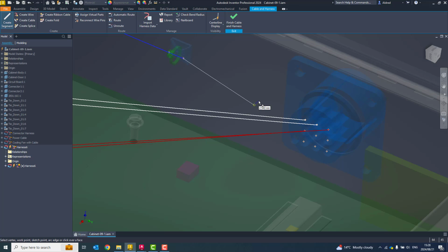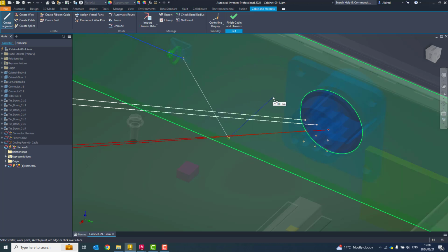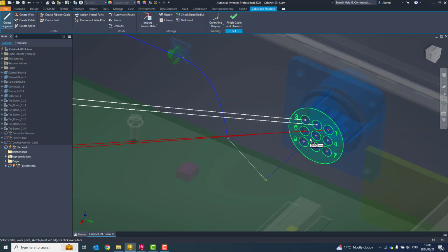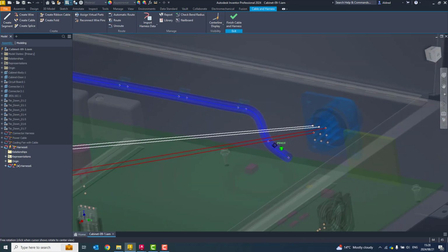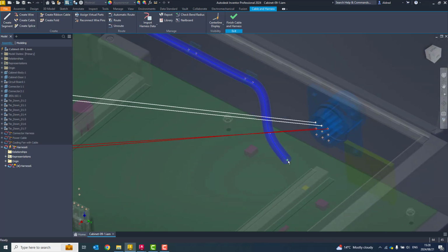Okay, so I've got a wire up over there. Okay, I'm just going to put a bit of an offset over here. So edit offsets, I'm going to make it 25, and then just make it 25 from there and from there as well. Okay, cool, I'm happy with that. Let me just move this in a bit, 3D move rotate, and just move it back over here so it doesn't look so messy.